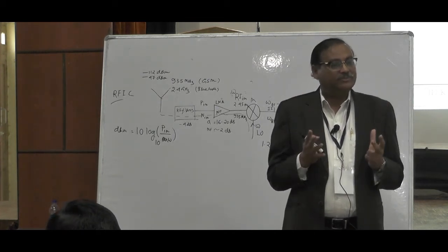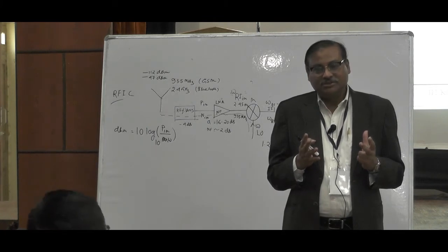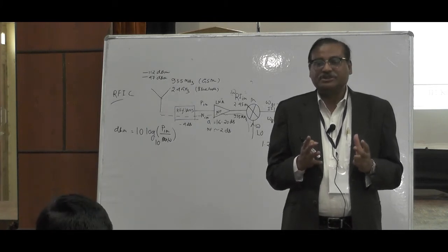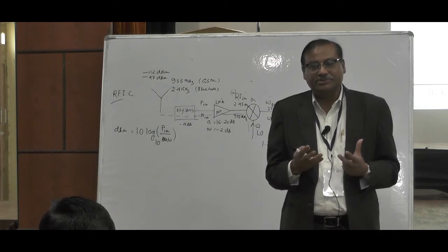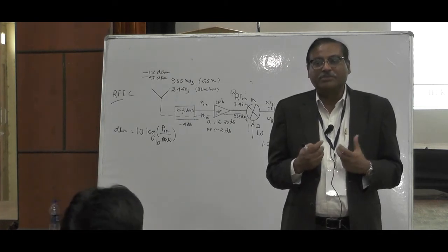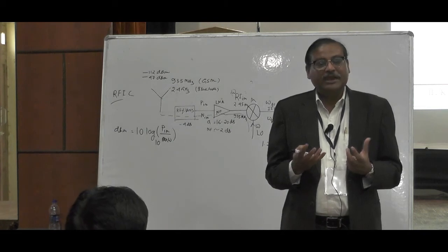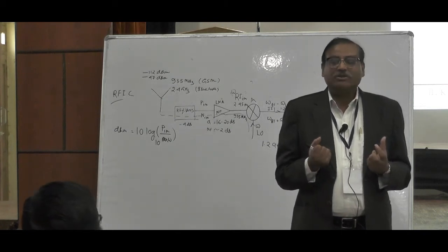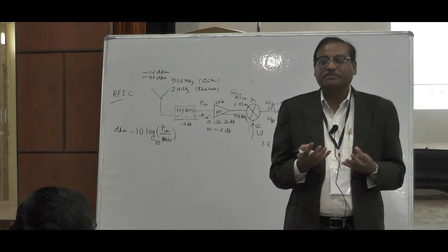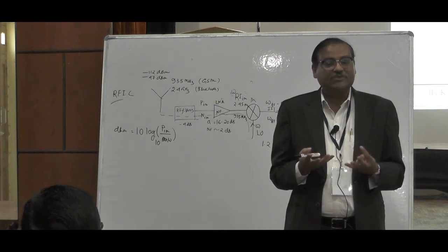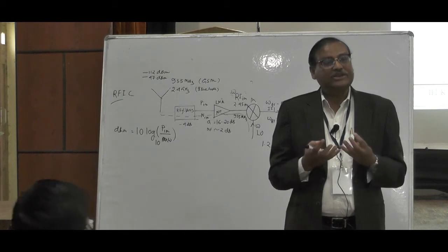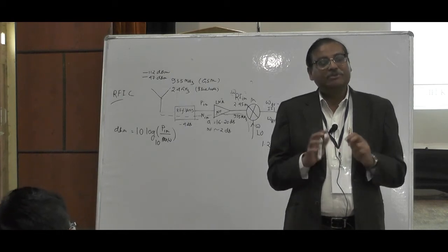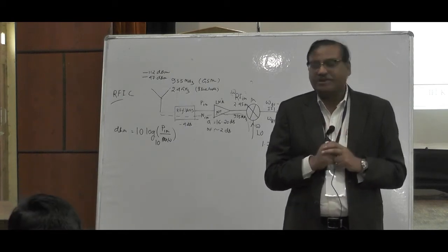You cannot avoid the front end just by introducing digital circuits, because then the circuit will consume so much power that heat dissipation will be prohibitively high. And second, you cannot have a super redundant kind of receiver where the hardware count is very high. So you have to have the kind of architecture where the hardware count is minimal.